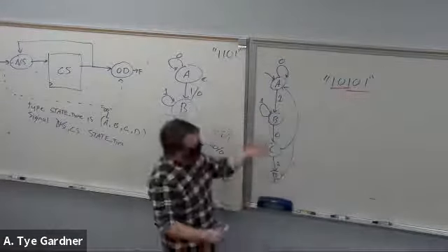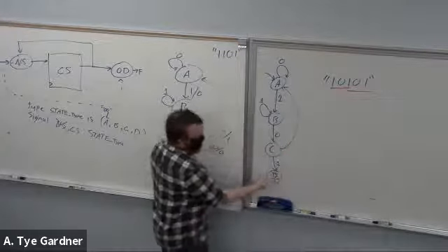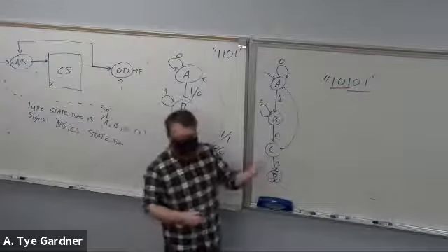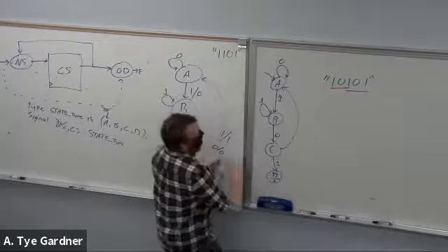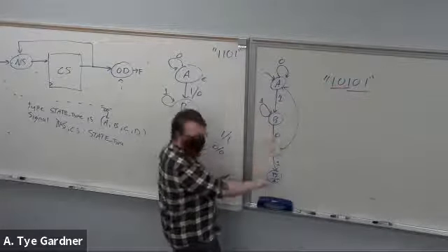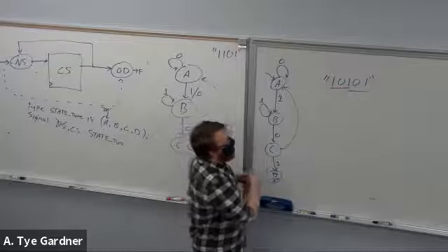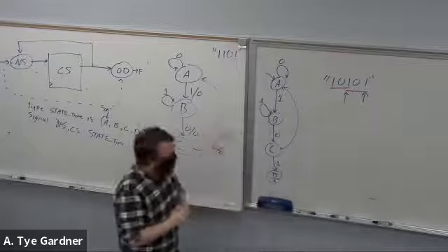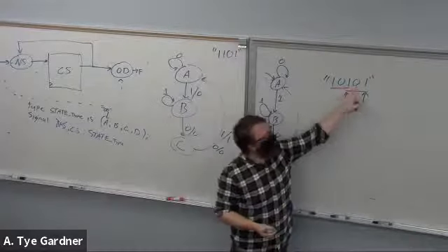So how do we do that in the Moore state machine? Well, we just change D, is all. That's the only thing we have to change. So let's think about it. We go ahead and we write the sequence that we want to detect first. So I would write the 1, 0, 1. I know that's what I want. Now I've got that detection, and I want to make sure that I get a detection here. So if I see this 0, where do I need to go to make sure that I can detect this one?